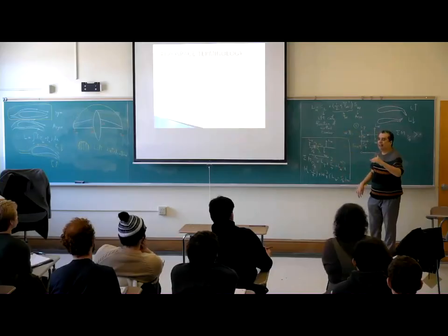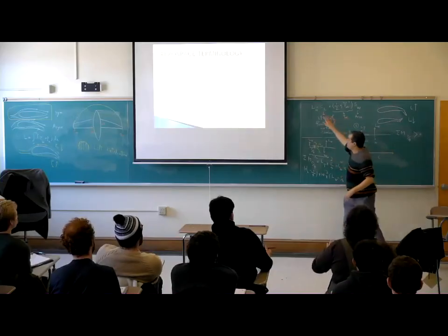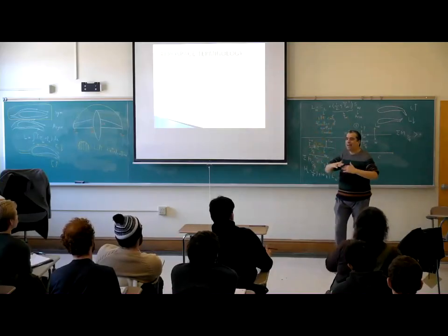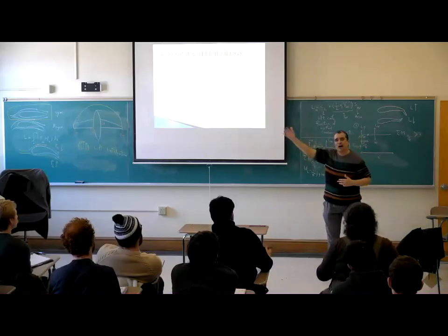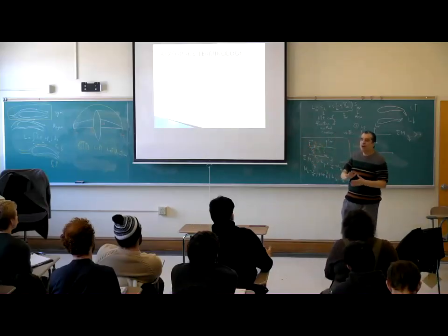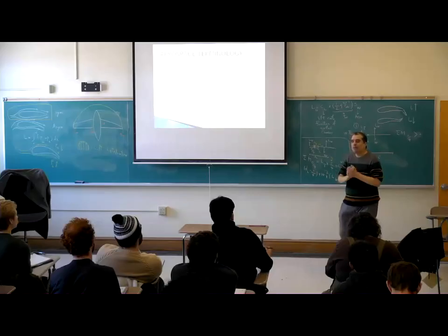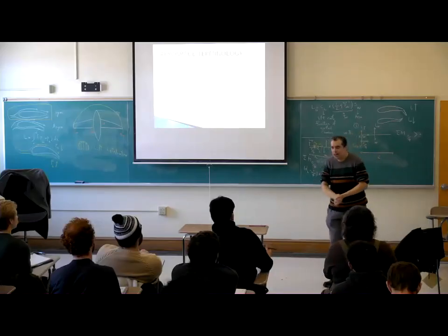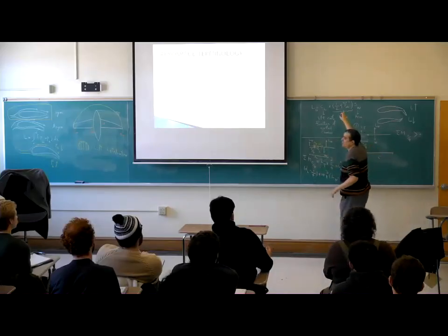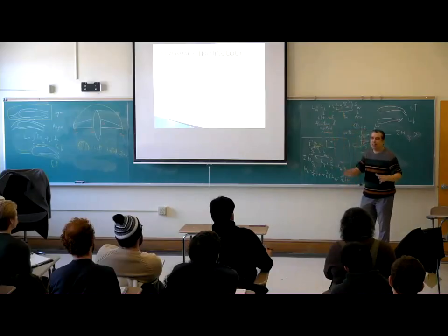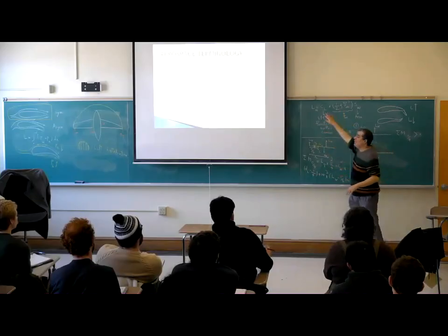Rho is high, so lift is high. You can carry more people in the sky. If we are in the winter and you are in Florida or Texas with a temperature of 100 Fahrenheit, rho is very low, so your lift is low.